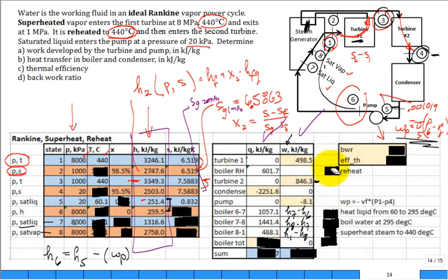We say, of all the heat that comes in to the boiler, okay, 17% of it is going into the working fluid in the reheat. Almost 20%. That's a lot. That's pretty good. And then to heat up the water, well, we're down to 29. Next time we're going to talk about making that much lower. To phase change 40 to superheat 14, counted for 100%.